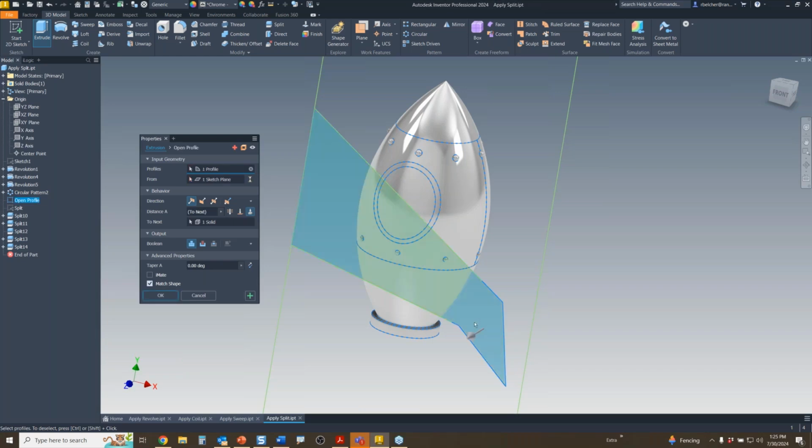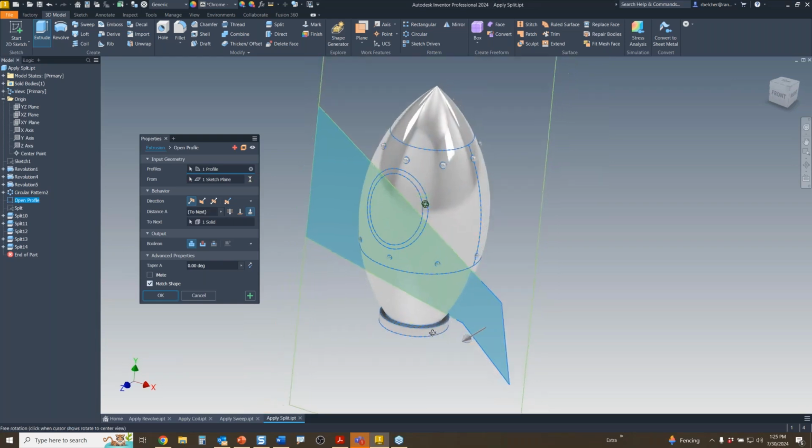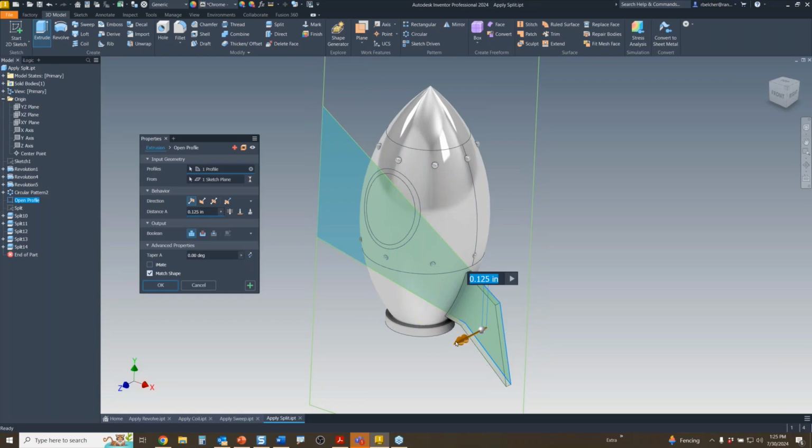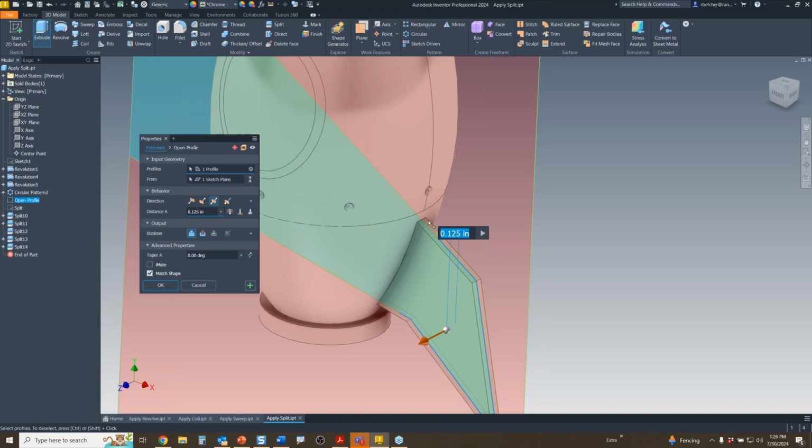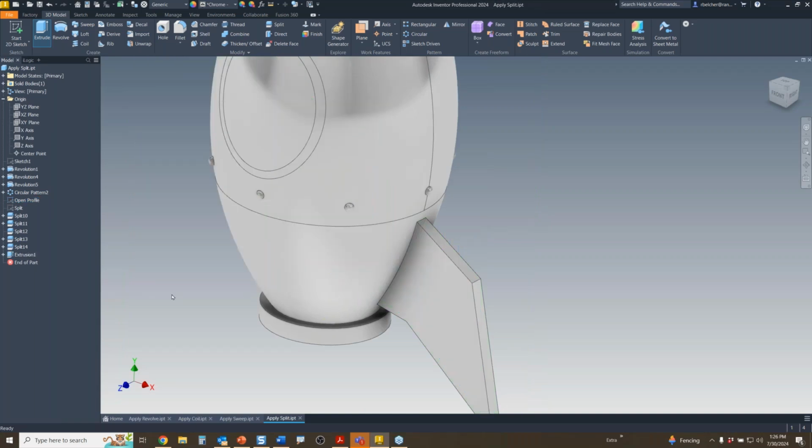So I can select this, and then I can arrange for just that particular area of the profile to be created. And you'll see that it's terminating against that cylindrical face, just like a rib would, or like using the To Next methodology. It works very, very nicely.